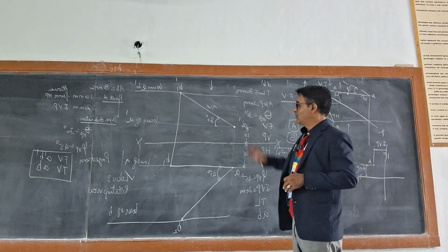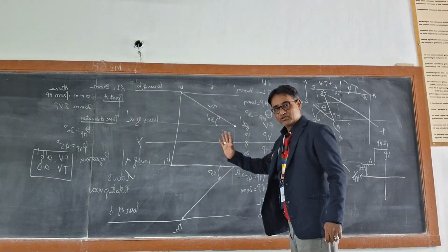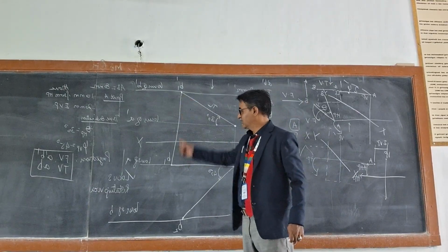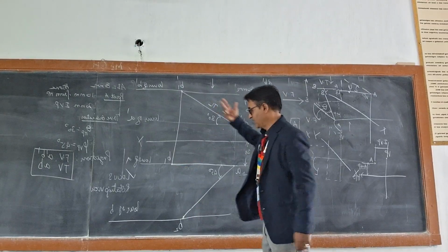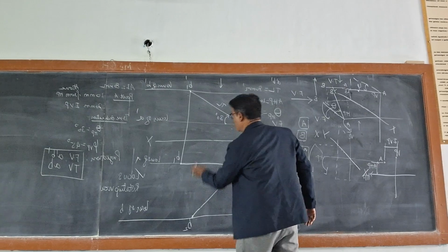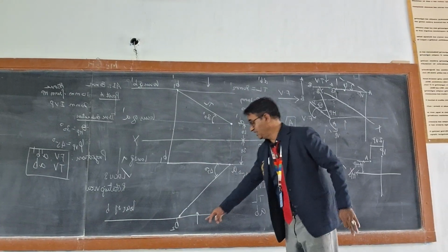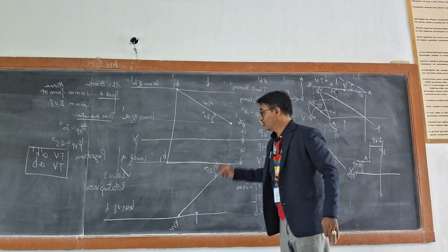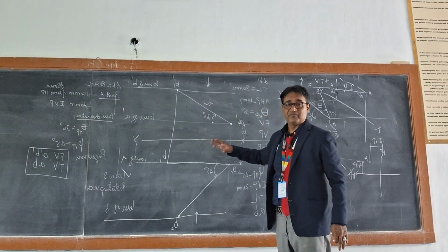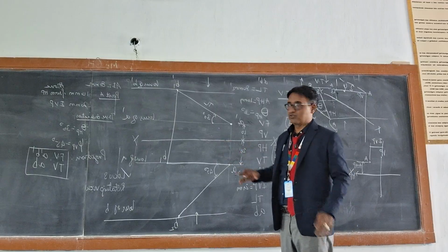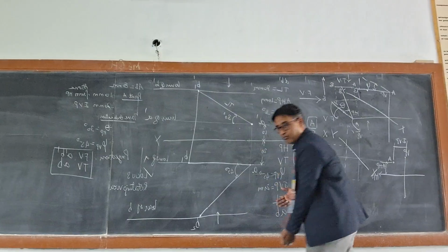Okay, now what I am going to do is, once you locate this, follow the same procedure. Here you have put a vertical drop, now you are going to make it an upward drop. So upward is B2. From B2, when you are looking from here, that doesn't mean that it is the bottom view, because I have told you the horizontal plane, vertical plane, everything you are using here is transparent. So from the top itself you look, this will be projected because you don't have any plane at the bottom.